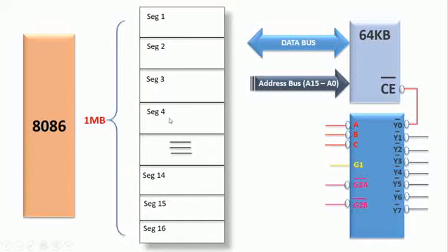In order to map this into the memory space, I am connecting one of the output lines of the address decoder to the chip enable signal of the memory device. And in order to choose one of the output lines, we are supposed to give the proper input combination. Which signals from the microprocessor should be used to drive these three input lines in such a way that it selects the Y0 output? That is the question.